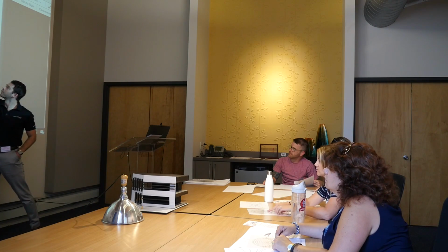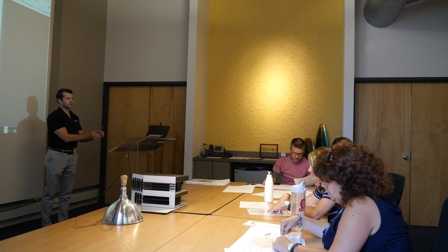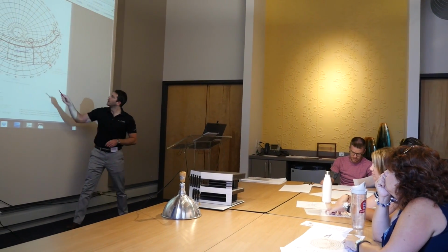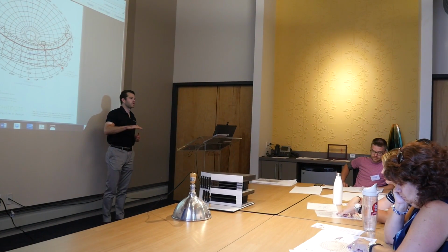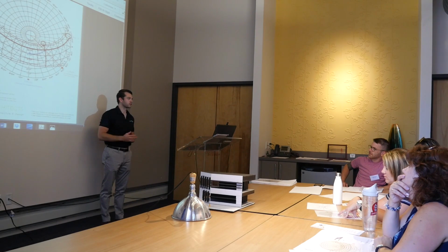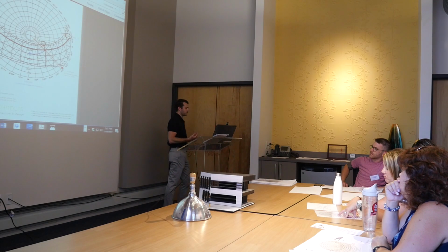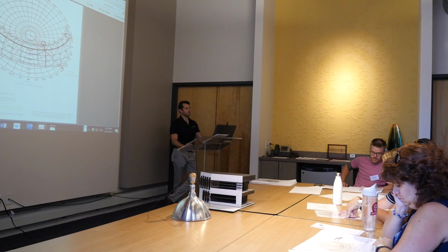And then if you follow from the center of the circle out, you can get your degree of where the sun is, at what angle the sun is hitting your building. And if you follow the concentric circles around, the red line, you can find what angle parallel to the ground it's hitting your building. So how high the sun is in the sky, essentially. And so with basic geometry, you've got 54 degrees off south is the angle that it's hitting your building. And I think it's about 51 or so degrees off the ground it's hitting your building.